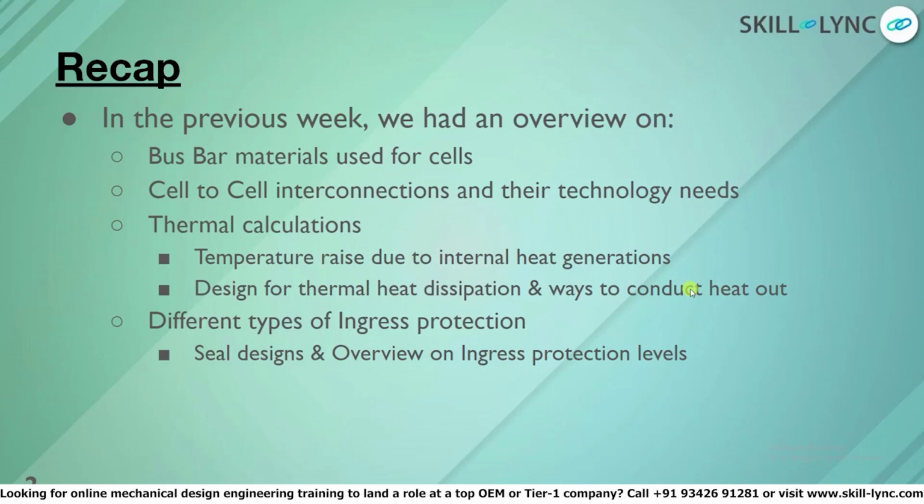What are the different thermal calculations to be done to understand the temperature rise due to the heat generation, which is a combination of internal resistance, SOC, etc. And we also had a session on ingress protection levels, what the different sealing types are, how the gaskets are designed, and what the different gasket materials used for the battery are. So this is a recap of what we did in week 2, and now what we'll have in